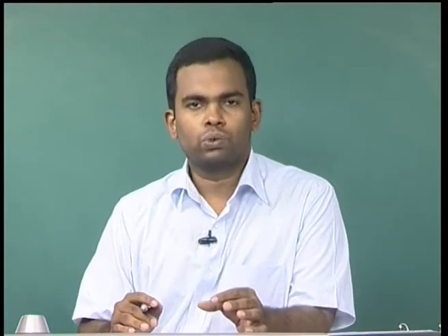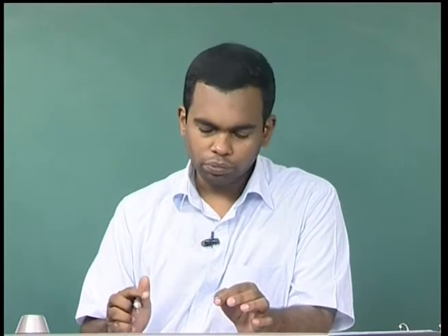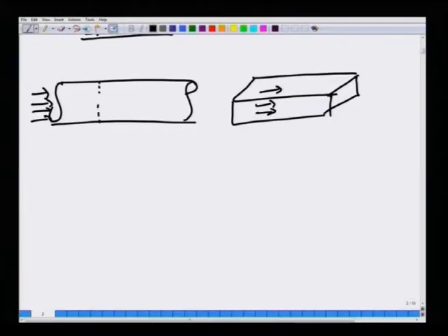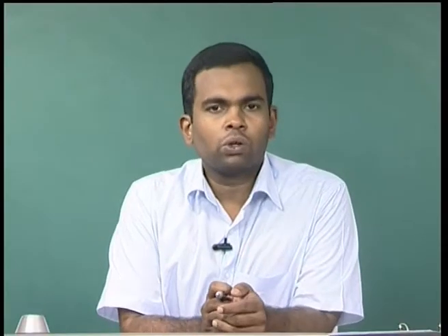Whenever we have flow through a duct, a pipe or a channel, regardless of the shape, it is experimentally observed that the velocity is not a constant, it varies with the cross section area. This is an experimental fact, and when we do differential momentum balances for a very tiny control volume, we will show this rigorously.